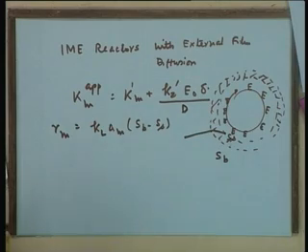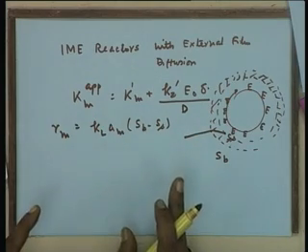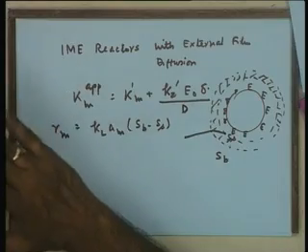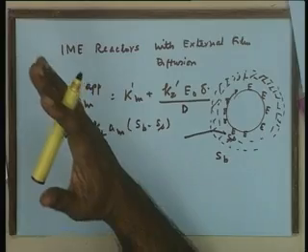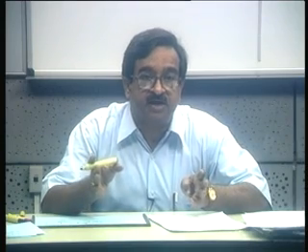The rate of mass transfer, the rate of diffusion in such a situation, let us assume that this particle, a non-porous particle, is packed in a packed bed reactor and you operate it till a steady state is reached. Steady state is reached means the concentration of substrate at the exit becomes constant with time. That means fractional conversion becomes constant with time. The reactor performance is under steady state, which essentially would mean that the rate of reaction and the rate of diffusion are the same. Rate of mass transfer and rate of reaction are identical.